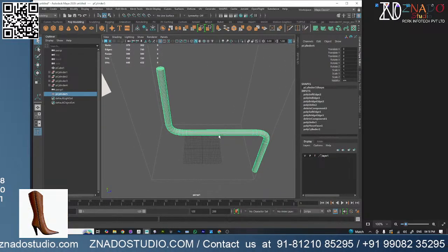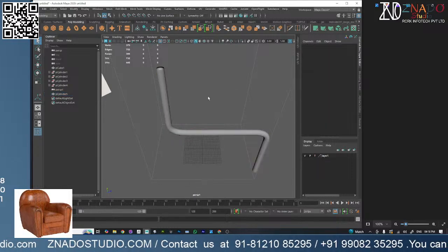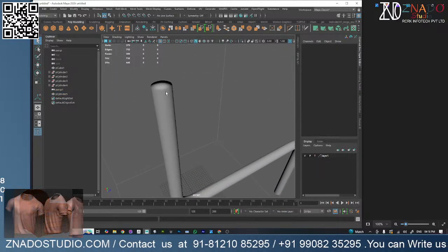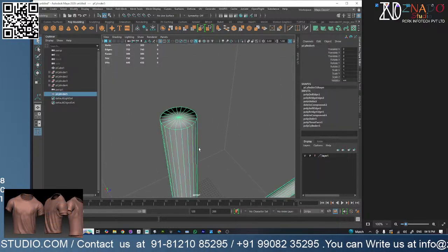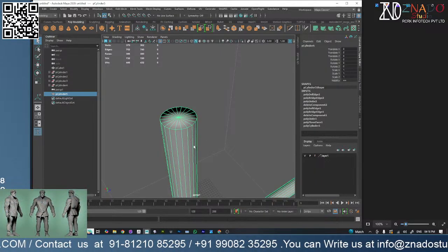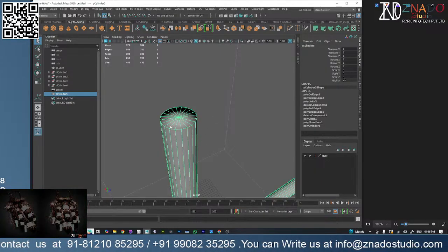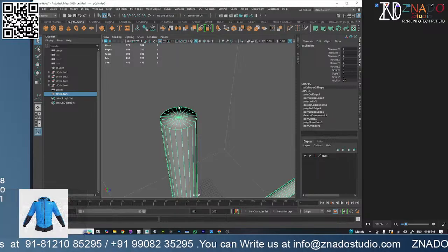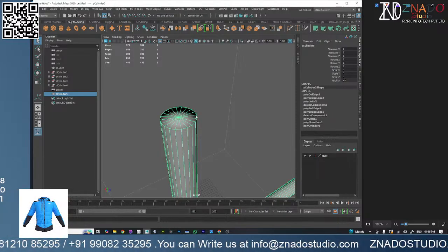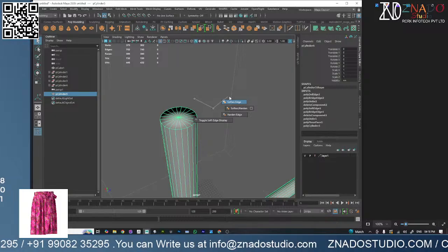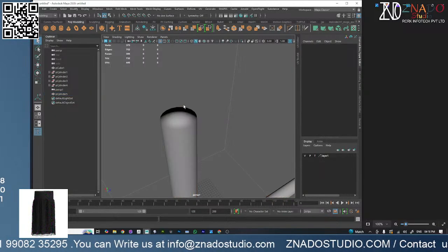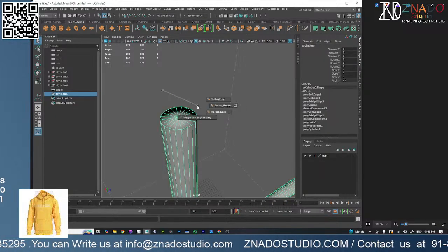What I did right now is let me show you. Whenever we are using soften and harden edges, wherever the object has some soft edges, it will make them softer. Sometimes these corners are sharp, so we want them to be sharp, so it doesn't do that when we do soften edges, so it looks like this black shadow on top, but we don't want it.